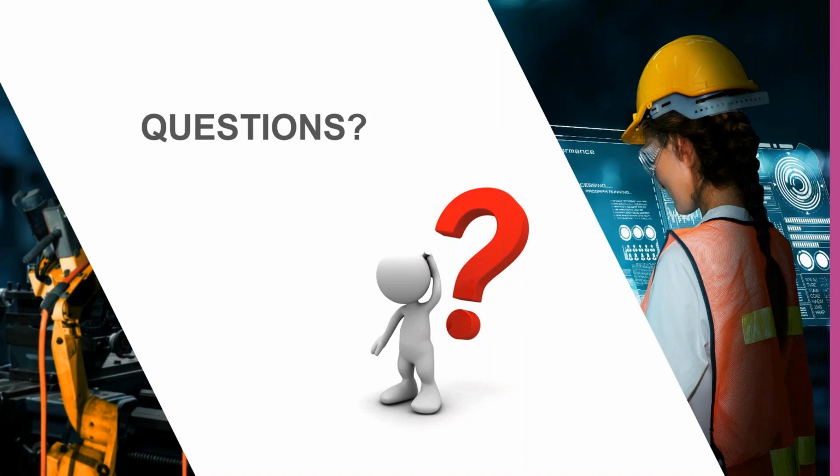And then your other question, can the MBD be used on detailed drawings? Well, they're two different categories. MBD is essentially the 3D version of detailed drawings. They're two different categories of features. So MBD as a whole, we're doing the same thing as we would be doing on a detailed drawing. It's just within the 3D part mode view.